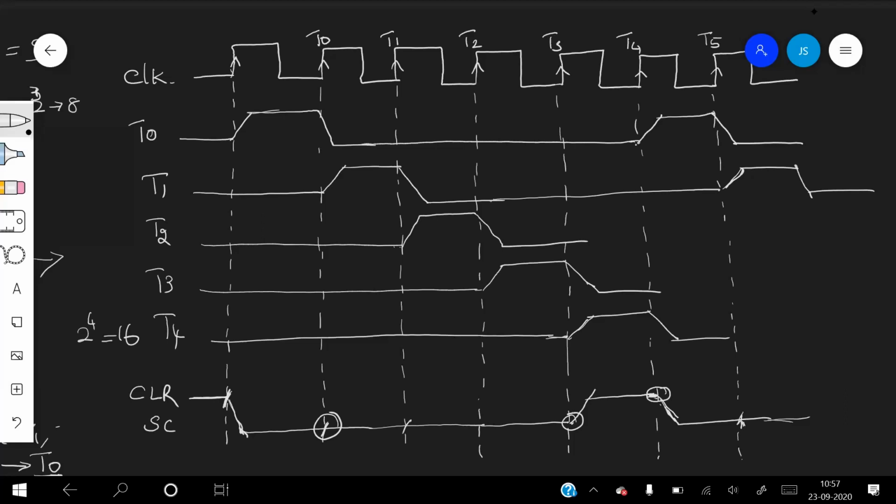This is how these timing signals are synchronously connected with the operations. A particular operation is to be performed, and when that particular control is active, the operation will be performed at the positive edge of the clock, when the clock goes high, for the positive edge triggered flip-flops or registers.